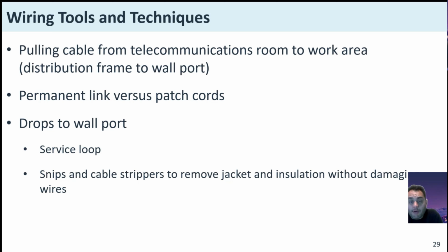Installing fixed cable from a bulk spool is referred to as pulling cable because the cable must be pulled carefully, meticulously, and measured from the telecommunications closet to the work area. Cable is normally routed through conduits or wall spaces, avoiding excess bends and proximity to electrical cables and fittings, such as fluorescent lights, as these could cause interference. Remember, you don't ever want to run data over power. You want to run them individually.